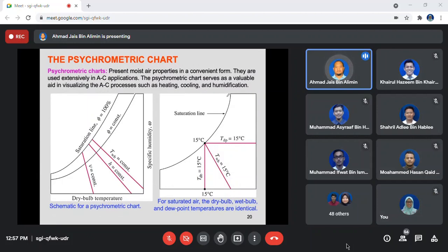Do not mistake that we use air conditioning simply to reduce the temperature. The temperature reduction that we choose using the remote control is just the surface process to control the amount of moisture. Okay, because it's much more practical to show to the users in terms of the temperature reading. But from the engineering perspective, we're talking about controlling the presence of the water vapor.